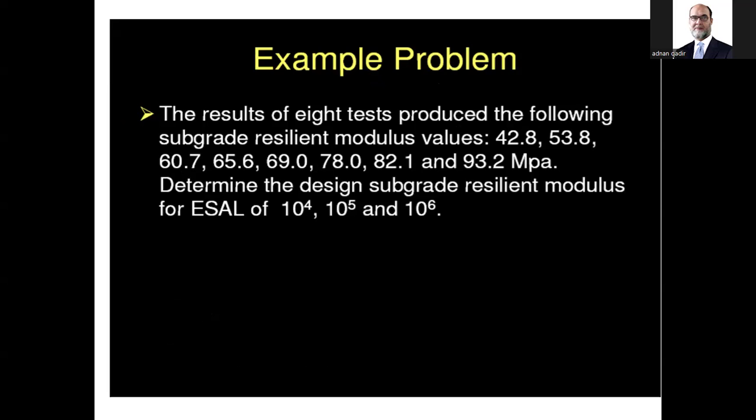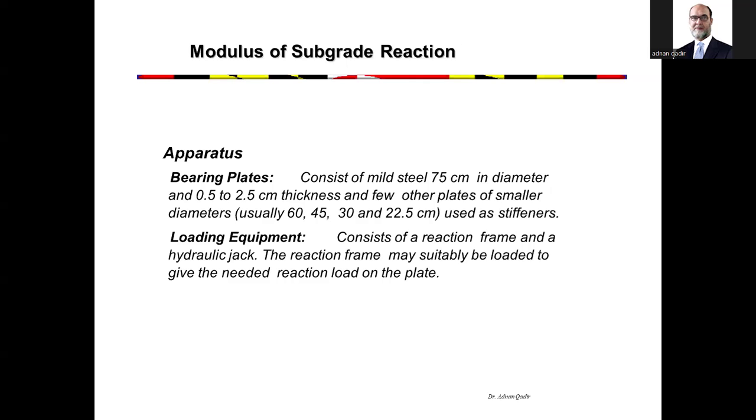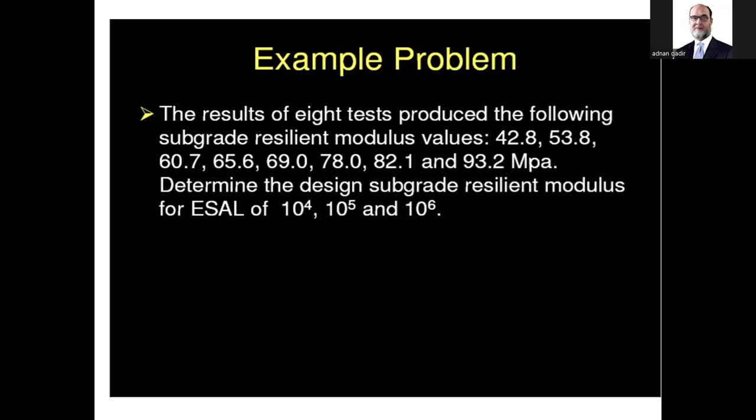Then you use that 25 or 55 CBR point. Or what you can do is another simple thing: take the representative CBR value and then convert it to MR. Don't get confused that you have to convert each CBR value into MR and then draw the graph. It won't make any difference. Take this design value and convert it to MR.